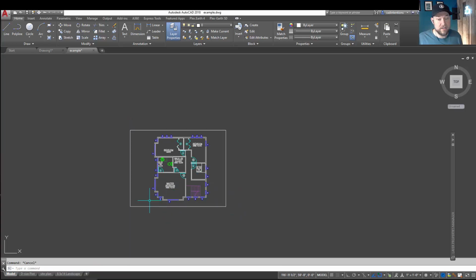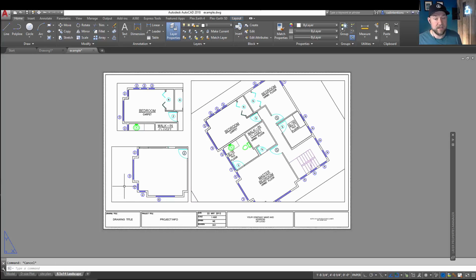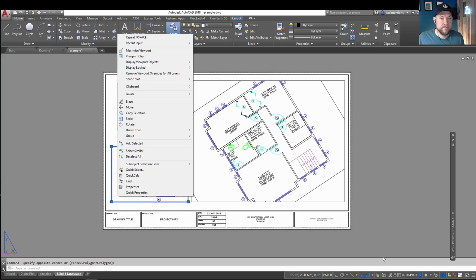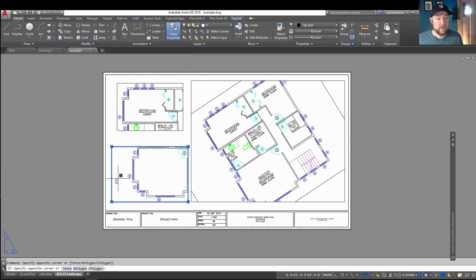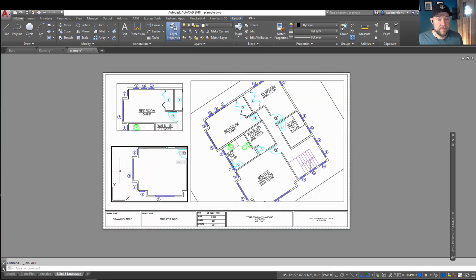And what you can do is go back to your viewport that you've got set up, and say for this one here, we're going to make sure it's unlocked up here, display lock, and it's a no. And we're simply going to zoom out. Now you can see that box we've created. You've got the ability to zoom.